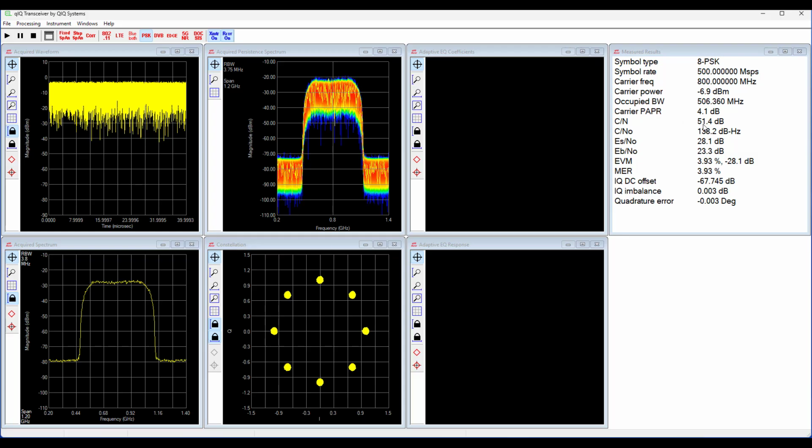And this value is 51.4 dB. This begins to set our expectation. This is just due to the spectrum of the signal and shows us how much carrier power we have compared with the noise floor of the receiver. We're hoping as we go through a whole demod process that we end up with a final set of symbols that has a similar signal to noise ratio.